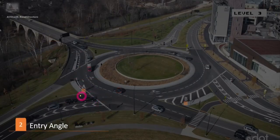It depends on the distance between the left side of the entry of interest and the left side of the immediate exit on the right, the distance between A and B. There are two different methods to measure entry angle. If the distance between A and B is less than around 100 feet, then the exiting traffic governs the method